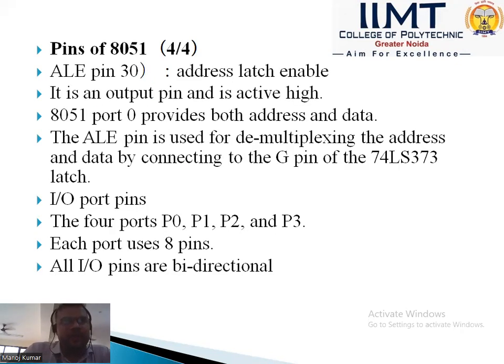This is the ALE pin, pin 30, address latch enable. It is an output pin and it is active high. The 8051 port 0 provides both address and data. The ALE pin is used for demultiplexing the address and data while connecting to the G pin of the 74LS373 latch.